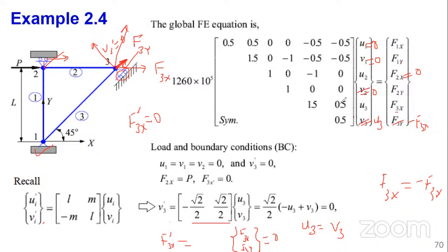So you see, you have reduced the number of unknowns. You only have U3 and U2 as unknowns. So you have simple equations in two unknowns. Okay, and then of course those which are 0, you can just go ahead and remove the rows and columns associated with them. You are left with just those associated with U2 and U3 to solve the equation.